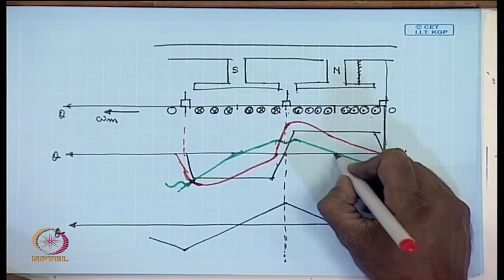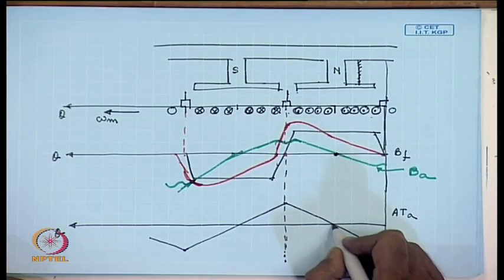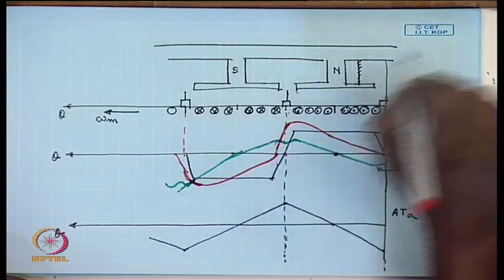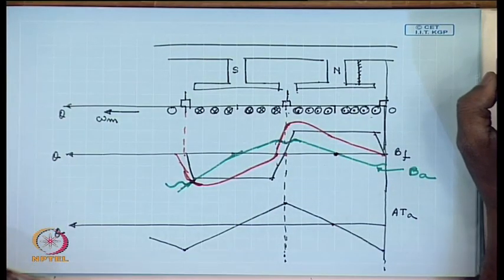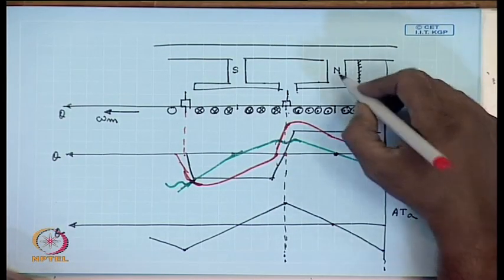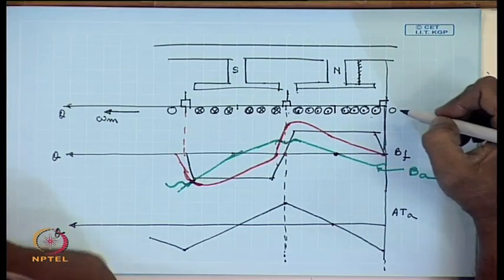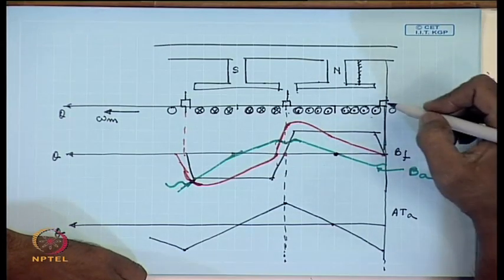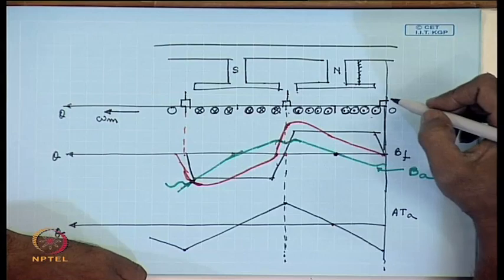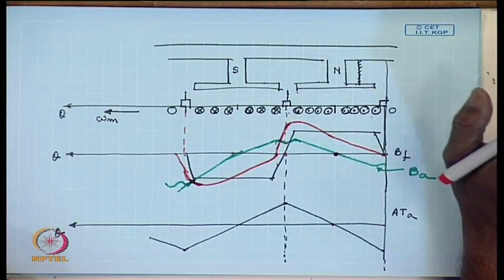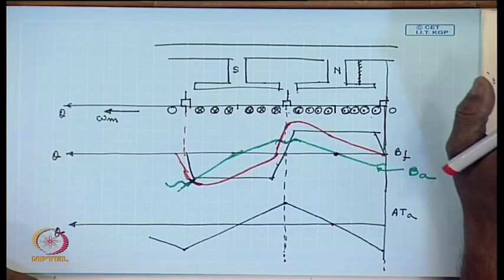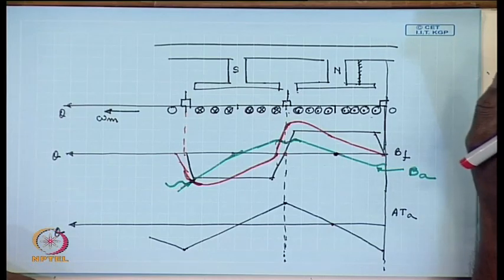The armature MMF peak coincides with the brush axis and its zero is usually at the magnetic axis called the direct axis, and therefore, there will be a distortion in the resultant flux.